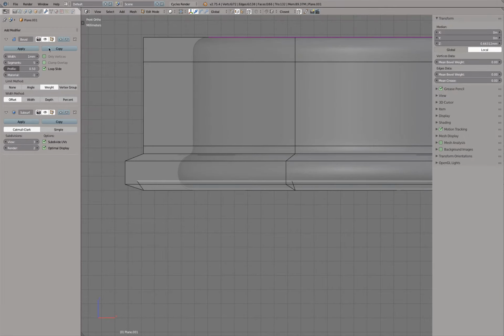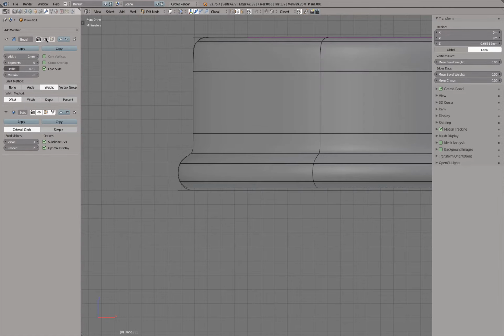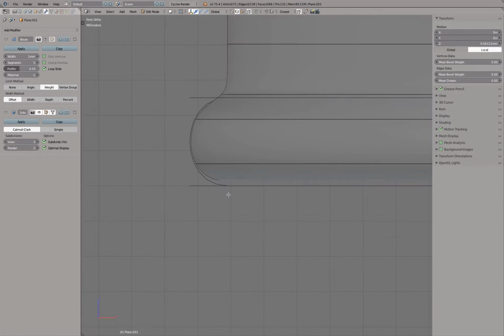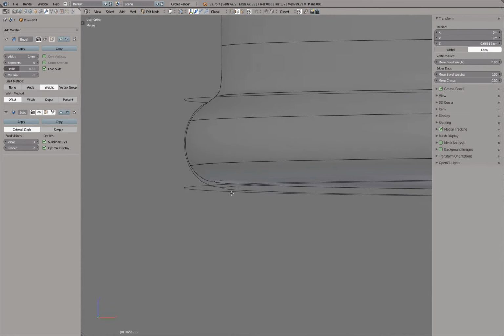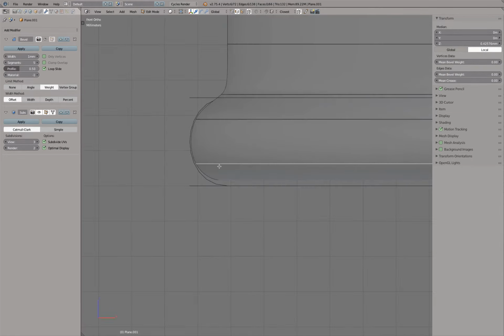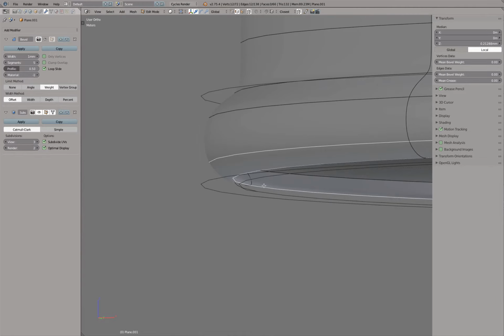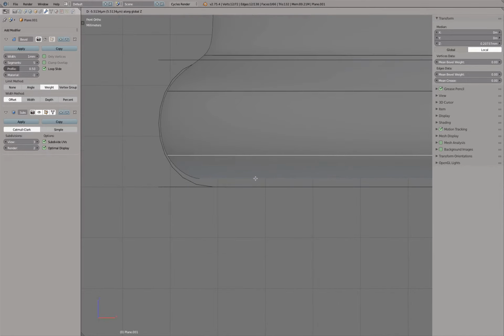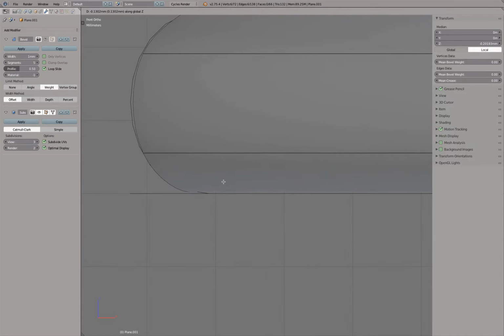So in this case, for example, what helps is turning off the bevel command, because then I can see how the mesh cage looks like. And I'm going to start and select, for example, those lines and then move them around and adjust everything a little bit so that I actually get back my original proportions there. I have to scale this one a little bit there, and then this one has to go down a tick more or scale a little bit.